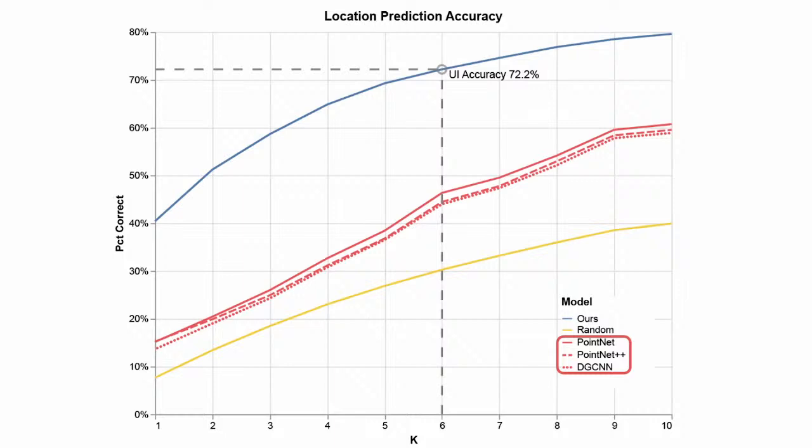I see. Basically what we say is that if the user clicks somewhere on the B-rep, that's how you select something in the system. Everything that's adjacent to what they clicked is considered a candidate for connecting, and then we find the combination of all the possible connection types there and rank those. Usually if you check every pairwise pair of entities, you get hundreds of thousands, millions of combinations for a complex object. We want to get some idea from the user of roughly where it connects. So we're looking at a local neighborhood.